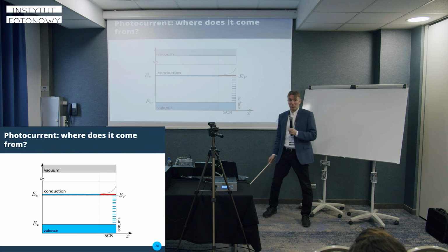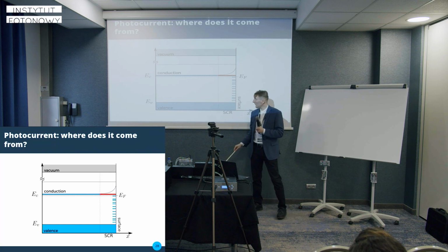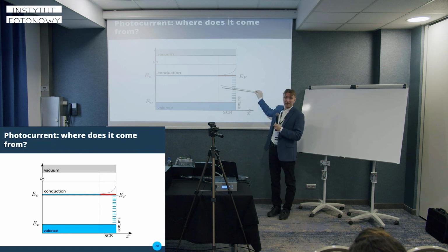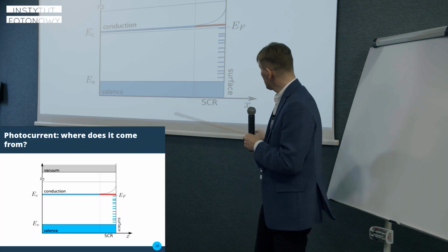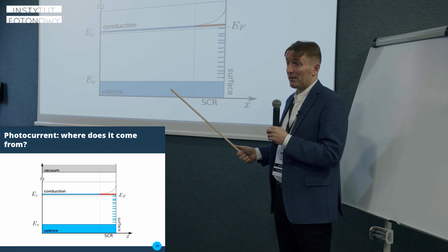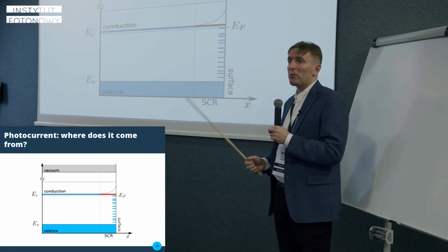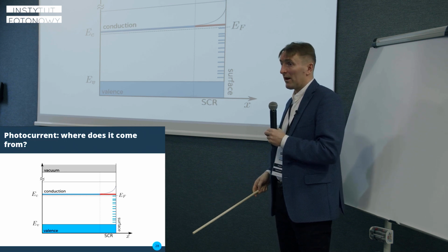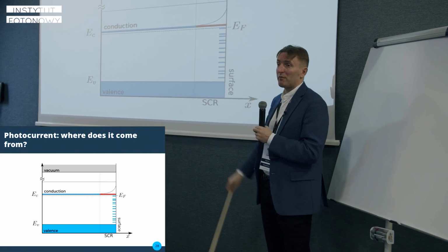However, there is no band anymore beyond this point, but we can have surface states. We forget about trap states and other things for now. Those are the only places, so the electrons will be sitting on the surface until you fill up all the states up to the Fermi level.